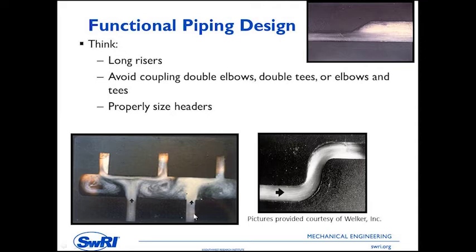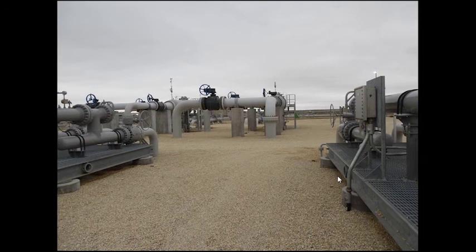But notice that flow divides on the first 2, but the third is not mixed. And I've had numerous people tell me, well, okay, if this was a header, for instance, a compressor station header, you're expanding into this big bottle, it's all going to mix. So if you had 2 different gas qualities coming in, you should get a common quality coming out. But actually the way that works is it's a first in, first out. You see, these 2 gas qualities will be the same, but this one will be typical of this line.